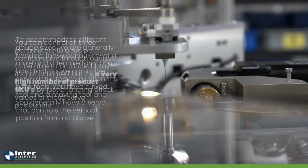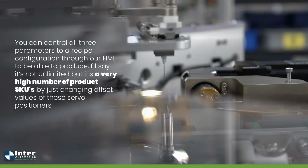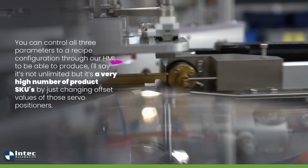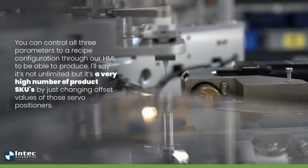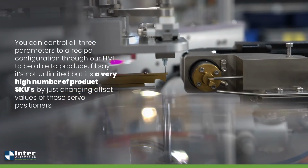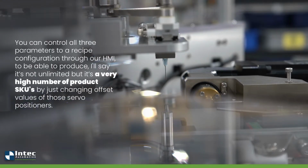And so we can utilize servo actuators to position the hard tools, whether you have a fixed tool and a moving tool, and then you have generally a servo that controls the vertical position from up above, where you can control really all three parameters through a recipe configuration through our HMI to be able to produce, I'll say it's not unlimited, but a very high number of product SKUs by just changing offset values of those servo positioners.